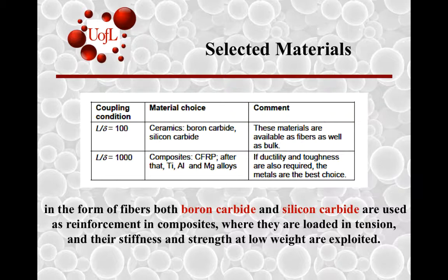When you have a small cross-sectional area, as in the form of fibers, then you can take advantage of the stiffness of the material, and you can eliminate flaws in tiny cross-sections much better, because you have a different synthesis route and you're really not densifying these fibers as you might for other ceramics in the bulk. So this is one type of exploration where you have multiple constraints and one single objective, which is to minimize mass.